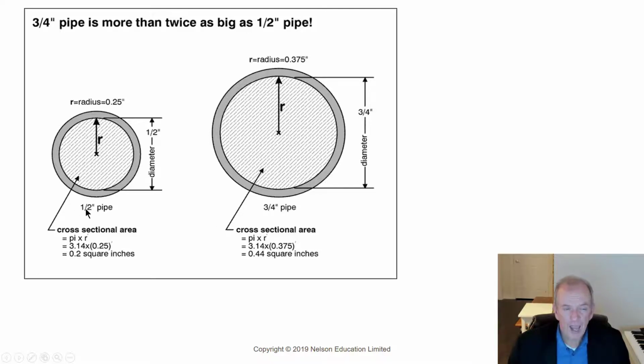So you go from a 1/2 inch diameter pipe to 3/4. Oh, it's not that much bigger. Well, actually it is. It's got more than double the capacity when we talk about area. And area is what's going to allow the water to flow. And you're going to have higher pressure that way in the pipes inside of the house, because they would reduce. Some custom homes will have 1 inch diameters, which now you're really getting massive amounts of pressure.